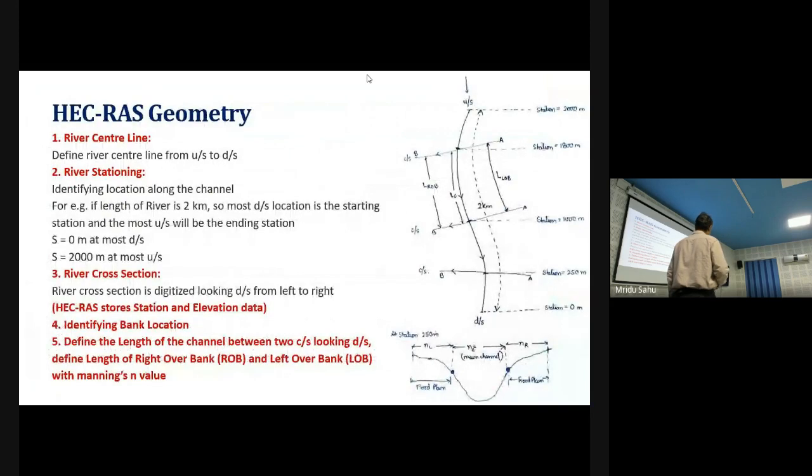This one. Okay. We take this as an example, right? So you are having downstream location. So start your cross section from the most downstream end. So station number name you can set as 0. You have to look from the most downstream point to the downstream end. After this particular location, any cross section you can see if you want to create.